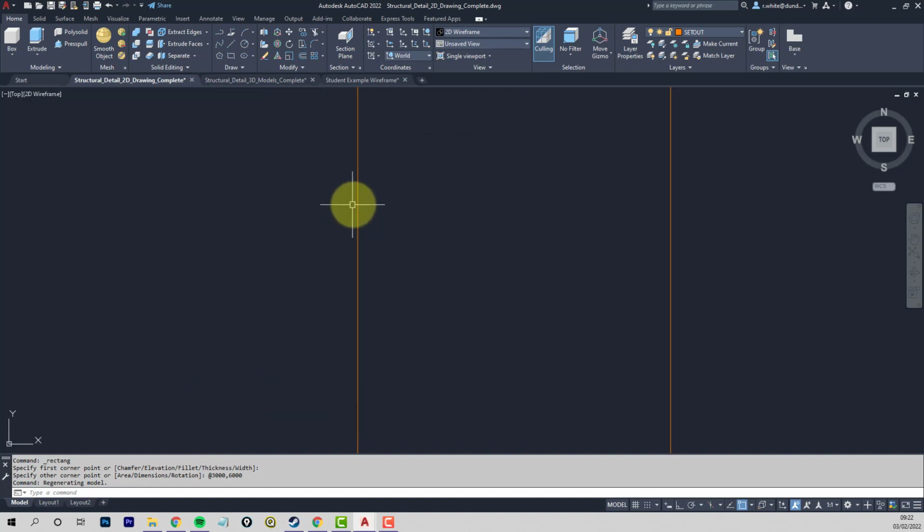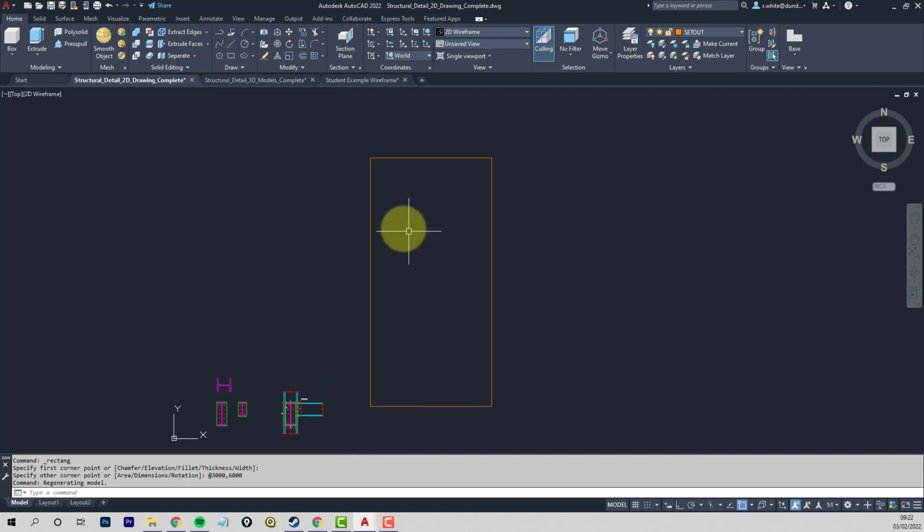If I zoom in, you can see there is a broken line, but the gaps and the dashes are too small for us to see. As we zoom out, we lose that definition. So the command to make the gaps a bit bigger is LTS, short for line type scale, and I think a value of 10 should be sufficient. I'll use capitals so you can read the commands going in a bit easier.